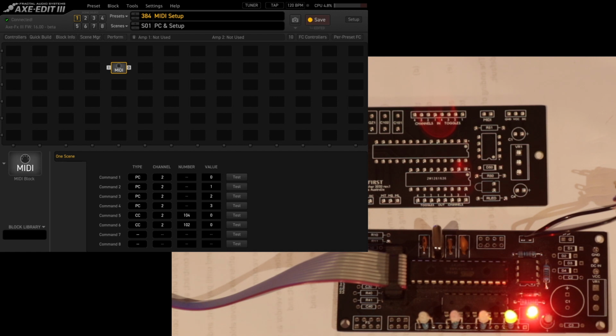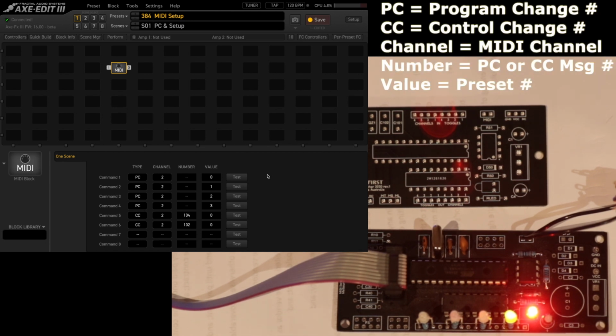Now in the documentation folder set out for these MIDI switcher boards, I've written up a couple of pages of documentation that describe exactly how this all works, and I've got all of these program change or control change messages that you would use to program the chip. So let's say I'm going to store a configuration or a setting, a set of relay settings into program 1, right? So this guy here. What you do is you select that program slot via a MIDI message.